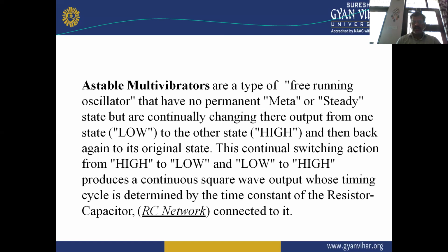This continual switching action from high to low and low to high produces a continuous square wave output. The timing cycle is determined by the time constant of the resistor-capacitor, RC, network connected to it.